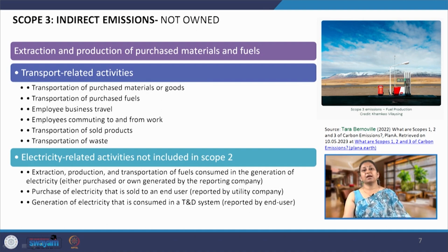For example, if I have to make a wall, I have the option of making the blocks as CSEB, compressed and stabilized earth blocks, which require no firing, no fuel, and a very minimal amount of stabilizer, which might be cement, and the clay, the mud, is procured from the site itself. Now, compare the emissions associated with the CSEB with an autoclaved aerated concrete block, the AAC block. The AAC block is completely made out of cement.